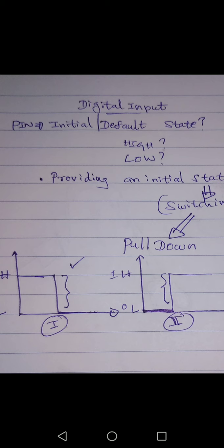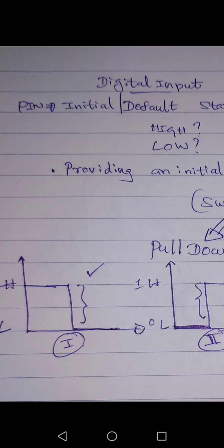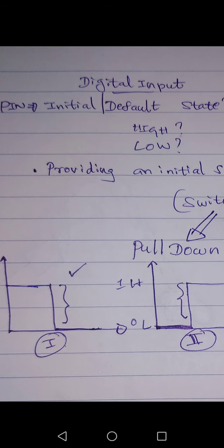to understand something. When you are using a switch or any digital sensor, and you are taking a digital input on a particular pin, let's say pin number 2, you are connecting a digital sensor or switch with proper connections to that pin. Before you read its digital state, that is why I explained the code at the beginning. You digitalRead and pass pin number 2, and you assign it to an integer variable. So it can be either high or low, 1 or 0. The digital input for the particular pin can be high or low.